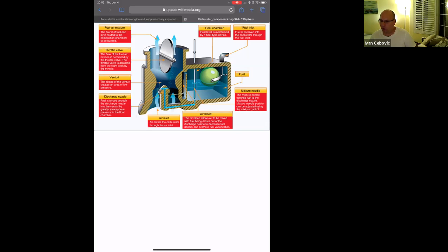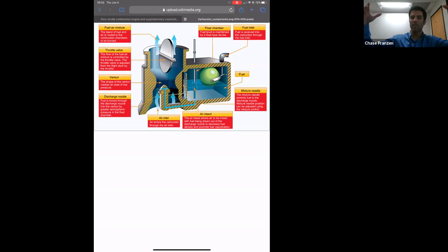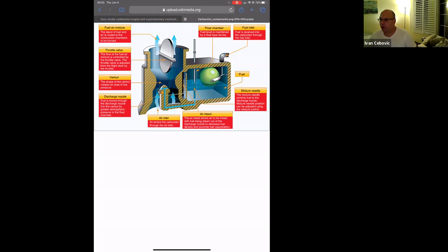And what about the vents? Why do we have 3 of them? What do they do? Much like a straw, if I put a straw in water and then put my finger on top of the straw and take it out, the water stays in the straw. Why? Because there's no venting on my thumb side, so the water can't flow down. It can't gravity feed. Because this is a gravity feed system, if there isn't a relief of pressure on the top of the tank, the fuel will ultimately not flow down the tubes and into the fuel selector. But even if it's mechanically fed, it can also be an issue, right? Sure, yeah, but this one isn't. There isn't a fuel pump in this model airplane, so I'm not bringing it up because you don't want the DPE to ask you about things that are irrelevant.